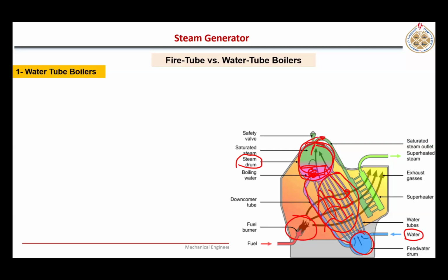So this steam which is produced is actually saturated steam, depending upon whatever pressure we want. This steam will leave, and here you see a superheater. If we want to heat that steam to a superheated temperature, here you see another heat exchanger, right? So this is a superheater. Here we can superheat with those combustion gases which are also flowing over this superheater.